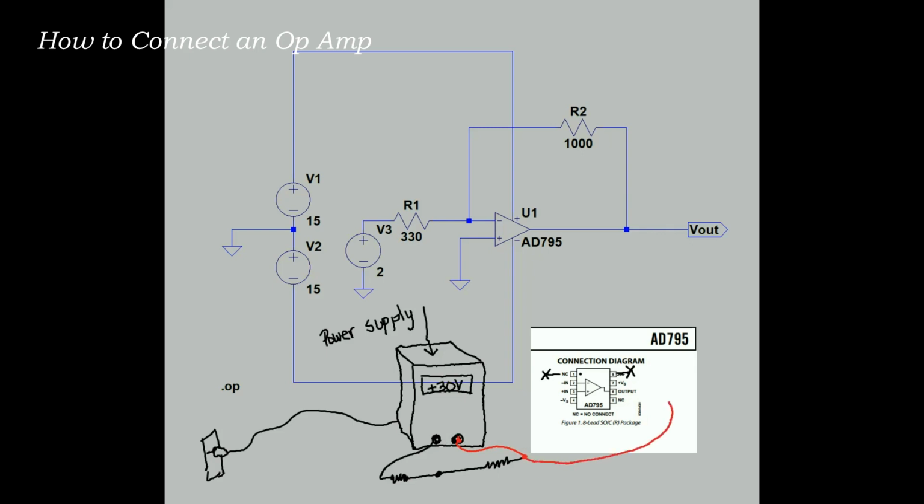There's really no purpose in drawing a lot of current. Now the positive terminal goes to your VCC, or plus V. Your negative terminal of the power supply goes here to minus VCC on the chip. Now this is going to be your common lead in the middle of the voltage divider. Common. Let's draw this in blue. So I'm not going to connect these, but they must be connected somehow.